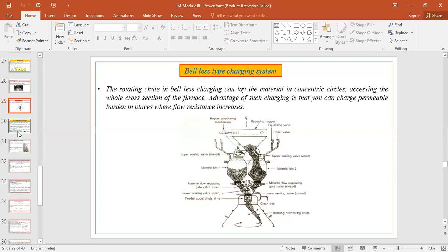Generation of a high quantity of fines inside the blast furnace is not good for the proper running condition of the blast furnace. You can lose the permeability of the bed, because of which the aerodynamics of the blast furnace will get hampered. Okay, so to make sure that the bed has good permeability, the blast furnace can run efficiently and effectively without any hanging or those kinds of situations.